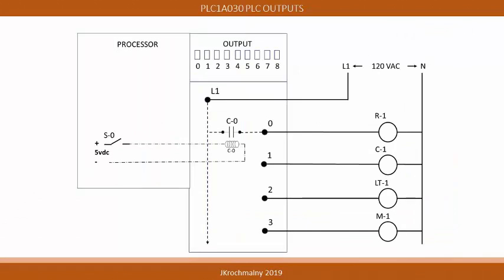In this graphic, we see a control circuit made up utilizing a 5-volt DC switch, S-0. This switch controls a circuit with a solenoid coil, which affects a set of normally open contacts identified as C-0. The condition of the contacts C-0 determine if the R1 load operates.